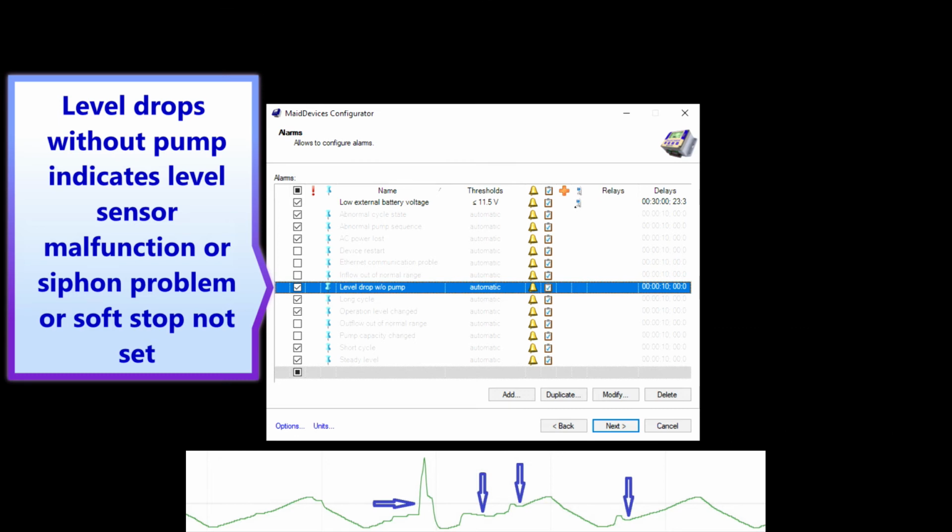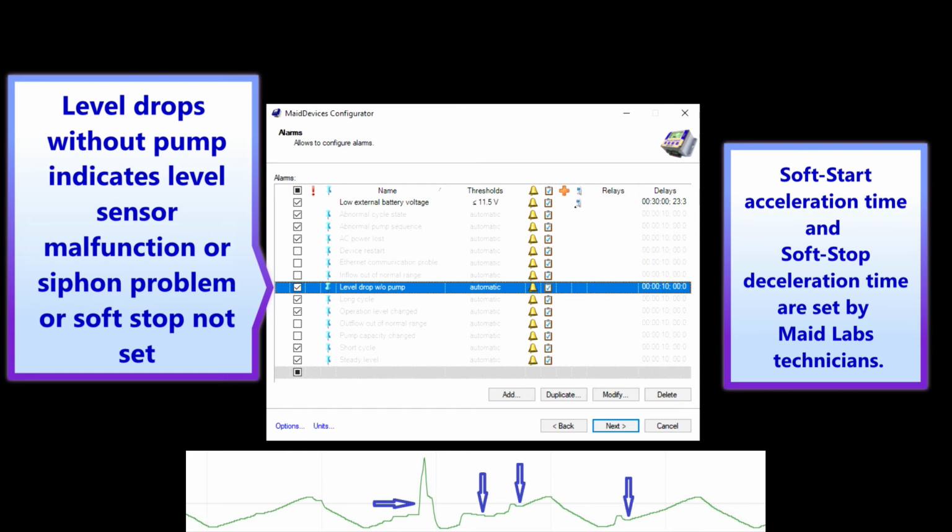The level analysis in self-made should be performed first to understand the true nature of the problem. If the pumps are equipped with soft stops and their deceleration time has not been programmed correctly, or programmed at all, then it is possible that the pump is still in operation when the current threshold considers it a stop. In this case, this alarm would appear at each cycle.